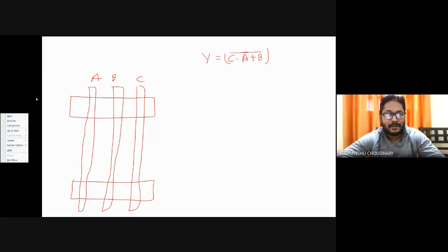Now the placement of transistors, right? The placement of cells or maybe placement of transistors is also very important. In fact, placement and routing, I mean how you will place the transistors on the layout or the chip and how you will route them, are one of the biggest challenges in digital IC design, in the layout design. So let us say we have A, B, C. They are sharing the diffusion regions. Now let us try to make connections.